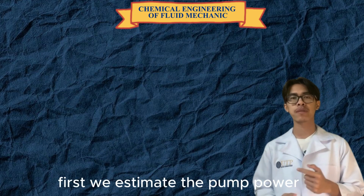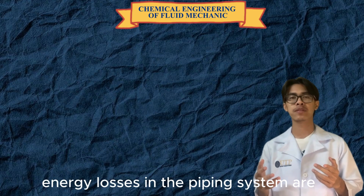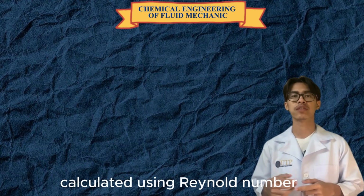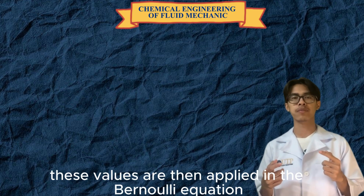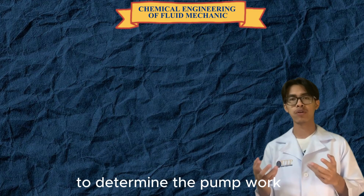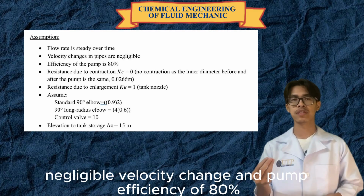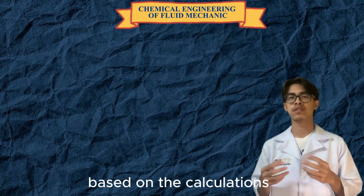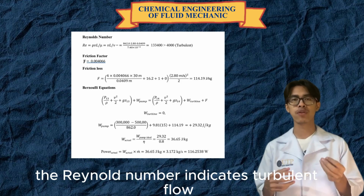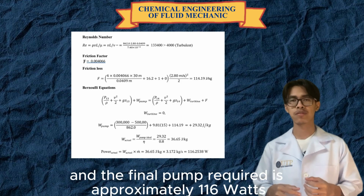First, we estimate the pump power required to deliver the main product to storage. Energy losses in the piping system are calculated using Reynolds number, friction factor, and friction loss equations. These values are then applied in the Bernoulli equation to determine the pump work. Several assumptions are made: steady flow rate, negligible velocity change, and pump efficiency of 80%. Based on the calculations, the Reynolds number indicates turbulent flow, and the final pump power required is approximately 116 watts.